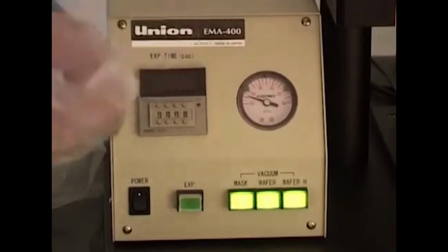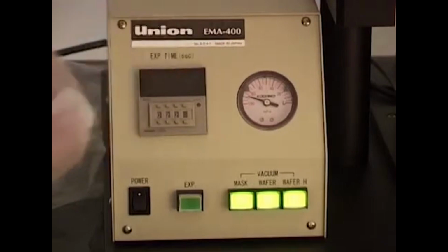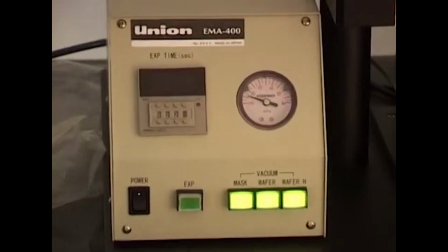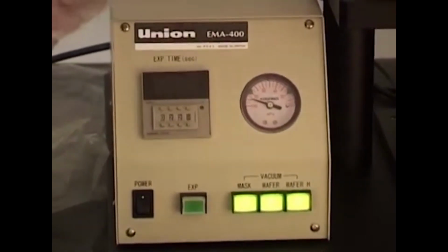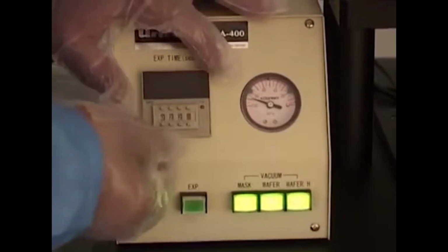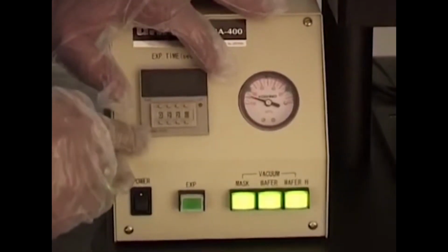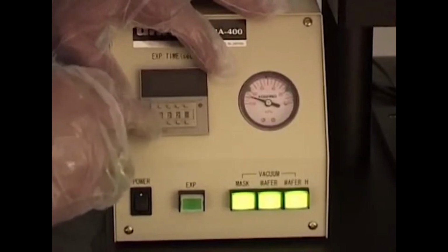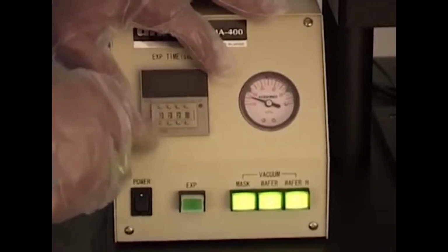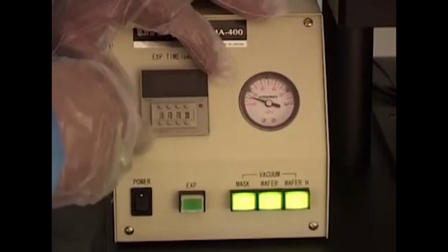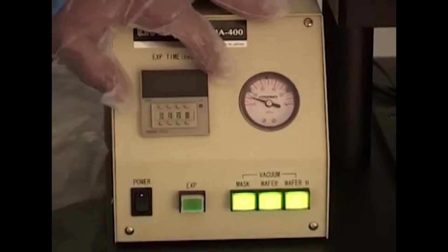Because our resist thicknesses are about 20 to 25 microns, we can get the correct exposure at the dosage rate that this particular lamp offers in a time of about 20 to 22 seconds. We use this timer setting for achieving that. You have these different values here in minutes, and right now the setting is about 22 seconds, which means the exposure would be for 22 seconds.